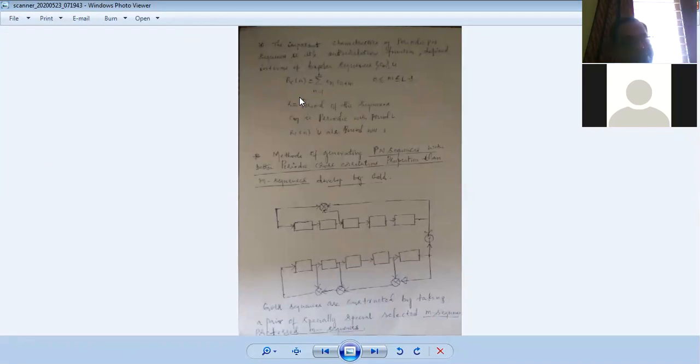So in order to enhance the periodicity between the different PN sequences generated, one more method has been developed, called Gold. See here, one of the sequences has been generated, and this other sequence of the pair is summed together with it, so the required periodicity will be generated. Right now, just understand that PN sequences will be like 1 0 0. This is what the PN sequence is.